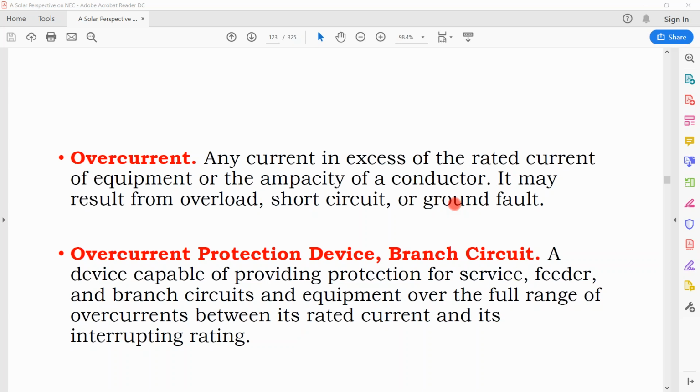such as when they're basing their calculations off a 90°C temperature and they land their feeders on a disconnect switch that's only rated for 75°C, and they didn't go back and see what size of conductor they needed to land on that terminal, given that terminal is given its temperature rating at 75°C instead of 90.